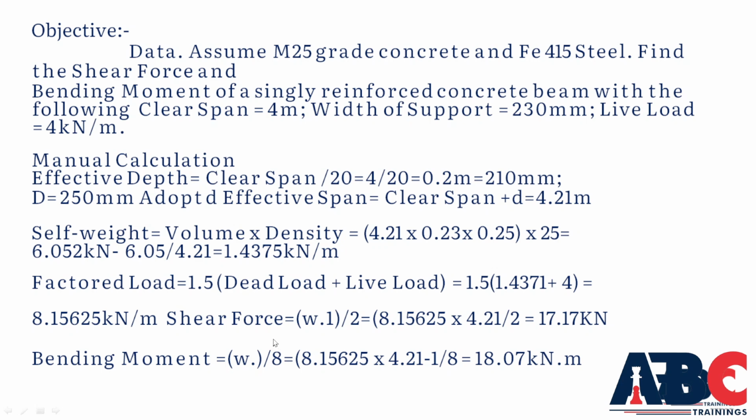Then the shear force is W times L divided by 2. It will become 17.17 kilonewton. Similarly, the bending moment formula for a distributed load is W L squared divided by 8. Then it will come to 18.07 kilonewton meter. Hope you understand this is the manual calculation for structural analysis.